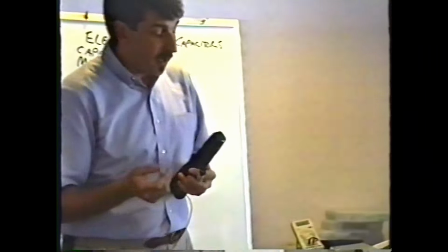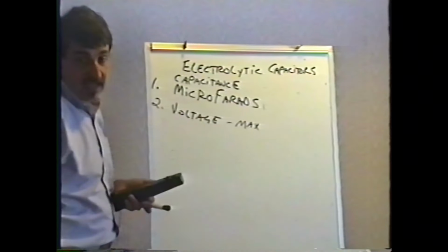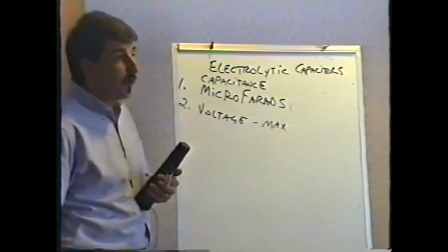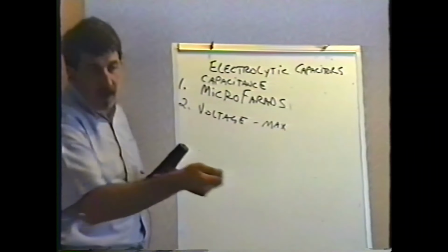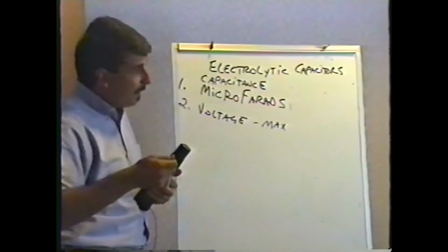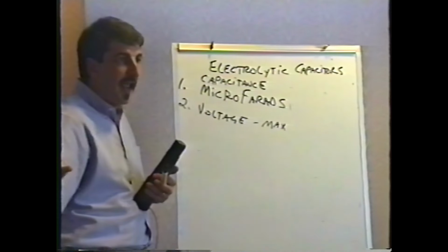But a couple of weeks ago I had to fix a monitor in one of the classes, and I needed a 10 microfarad, 16 volt capacitor. I used the 10 microfarad 200 volt. It works fine. Remember, the voltage rating of a cap isn't how much it puts out. It's not going to put out 200 volts. It's the maximum it can handle.